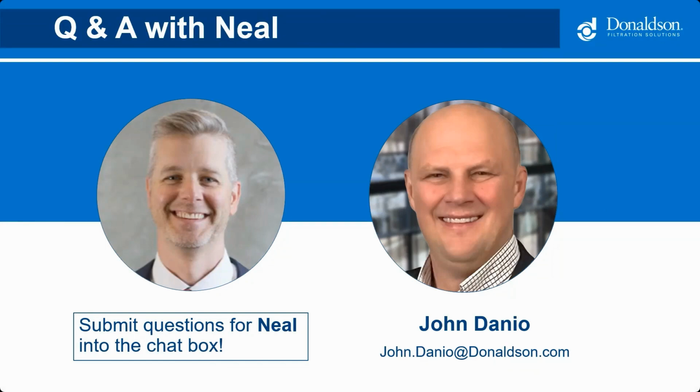This person's asking about the static pressure in the main duct. So the question is, what is the static pressure in the main duct? I'm thinking maybe it's probably related to how to determine what it is. It really depends on the layout of the ductwork, right? If you just have a straight duct, you have very low static pressure. It's dependent on what the diameter of the ductwork is, so that area, what your velocities are, and how straight the run is. So for example, a 90-degree elbow might have a 1/4 of an inch to a 1/2 inch of static loss, depending on the sizing. So it's really dependent on what your duct layout is.